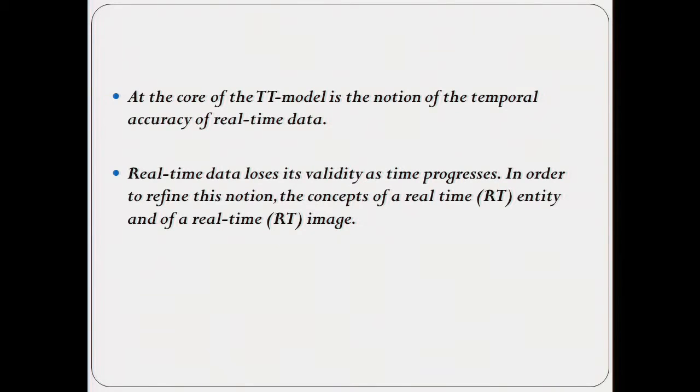So the decision on the slot to give to each node is one decision, and the second decision is how long the entire cycle is. So you have to decide these two things. And so the design, for example, of a good TDMA TTP network is to decide these two parameters, the window and the slot. And it's a very interesting mathematical problem, by the way.